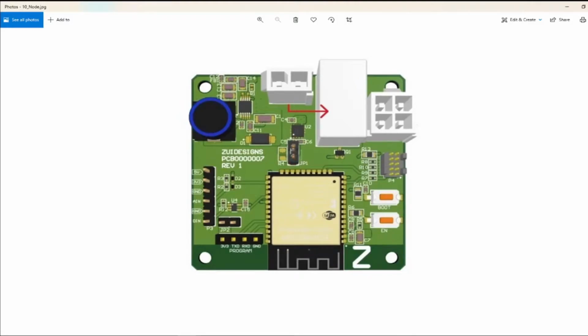Supplied power is also routed to a relay switch that can be activated and deactivated by the ESP32 module. This allows the supplied power to also become a board output for powering external devices. The design has the ability to sustain up to 10 amps of current, which provides the option for nodes to control power-intensive devices such as motors and solenoids.